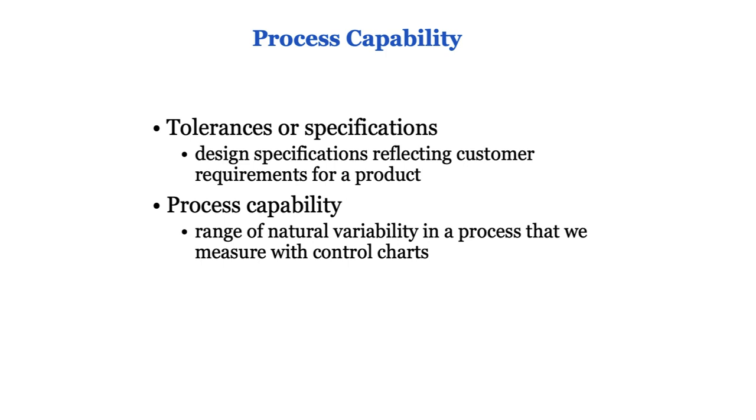The second process change that can occur is a change in the variability of the process, in the spread of the process. This is reflected when the sample range or standard deviation increases or decreases. Similar to changes in the central tendency of a process, a gradual increase or decrease in process variability often indicates fatigue or wear and tear, while an abrupt and sustained change often indicates the effect of a shift change, a new employee, or changing raw materials.